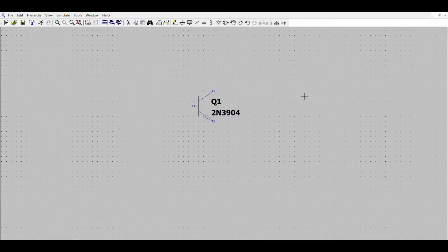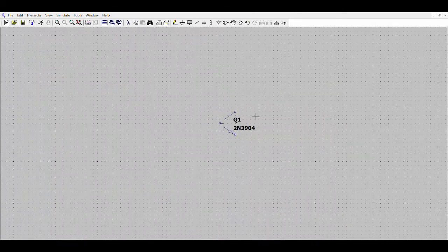And by referring to the circuit in the lab sheet, we can add an NPN BJT to the circuit here in LTSpice. It was asked to use a 2N3904 for this experiment. And then we add more components to the circuit, which is this resistor